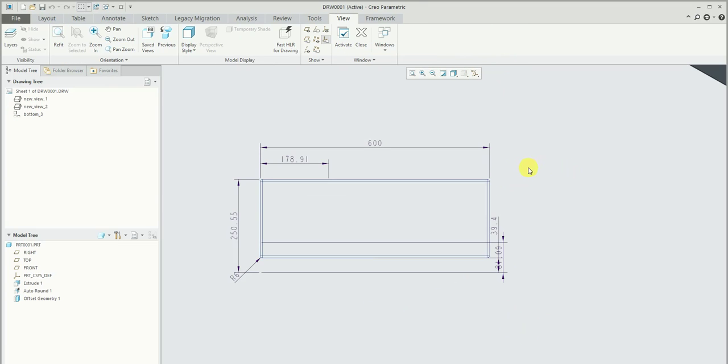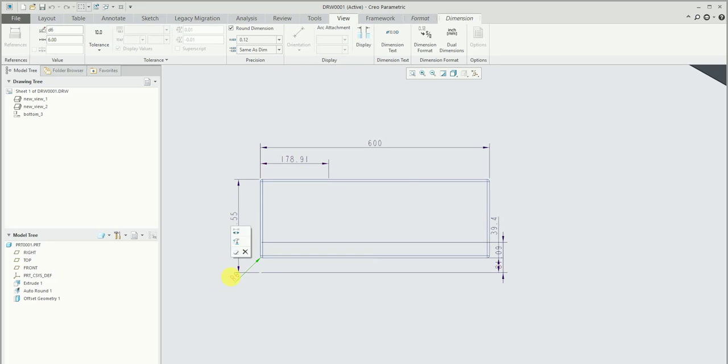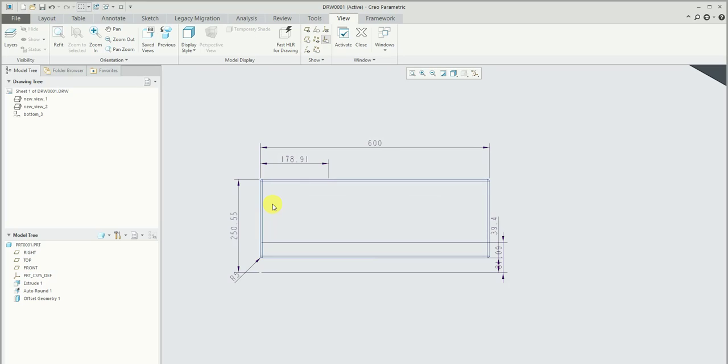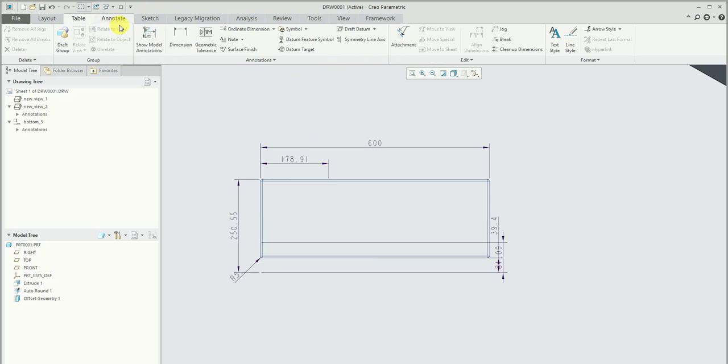I like it. If you want to make a change at one place in drawing mode, like you came to know that you need to make a certain change, then you can directly make it. For example, radius, I don't want to make it 6, I want to make it 5. But keep in mind that this only happens with the driving dimension, and if you create a draft dimension, then you might not be able to do that.